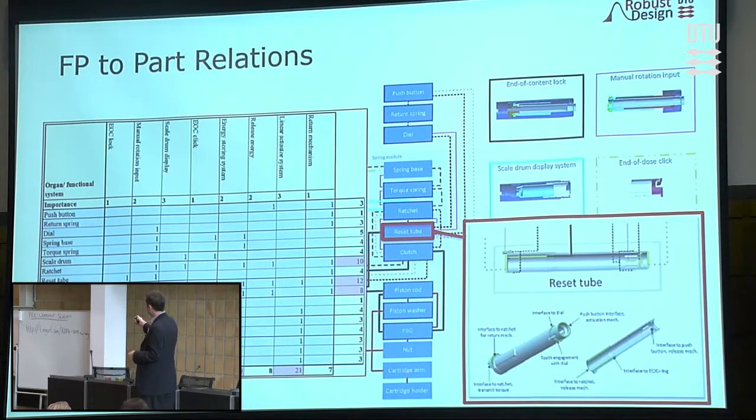And we can actually say, when we look at the function requirements listed here, so the matrix is inverted, we can say which of the function requirements are the most coupled to numerous design parameters. So we can say, is that a problem? This is a critical functional requirement, and it seems to be dependent on numerous design parameters. We can also say which components are linked to the most functions, and we can identify critical components and then the sequence in which we want to set the dimensions and tolerances for each of the components. But this is useful and interesting data just at this simple level. And it's not really asking us to do any more.